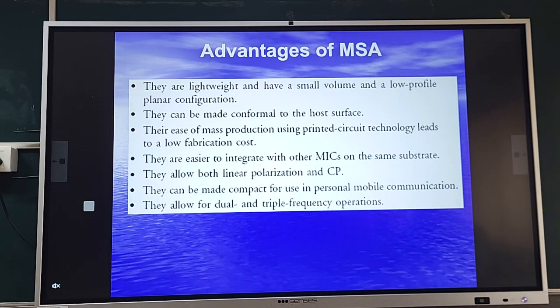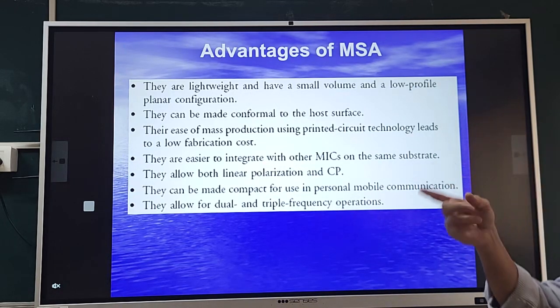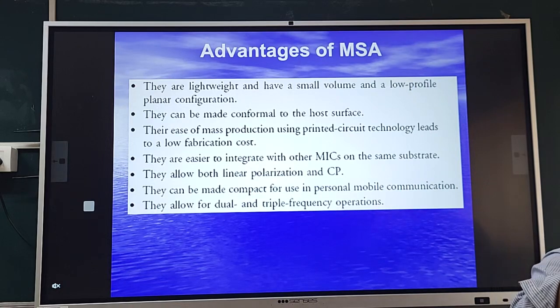Means what? At 900 you have jamming, switch over to say 1100 megahertz, switch over to 1300 megahertz. So that kind of frequency hopping is possible because microstrip antennas with dual, triple and multiband facility are easily possible using a single patch. That frequency ratio can change with respect to the antenna design you are considering. Means what? 900 to 1100 to 1300, like these frequency hoppings are dependent on the selection of the microstrip antenna patch, but that is very much possible.